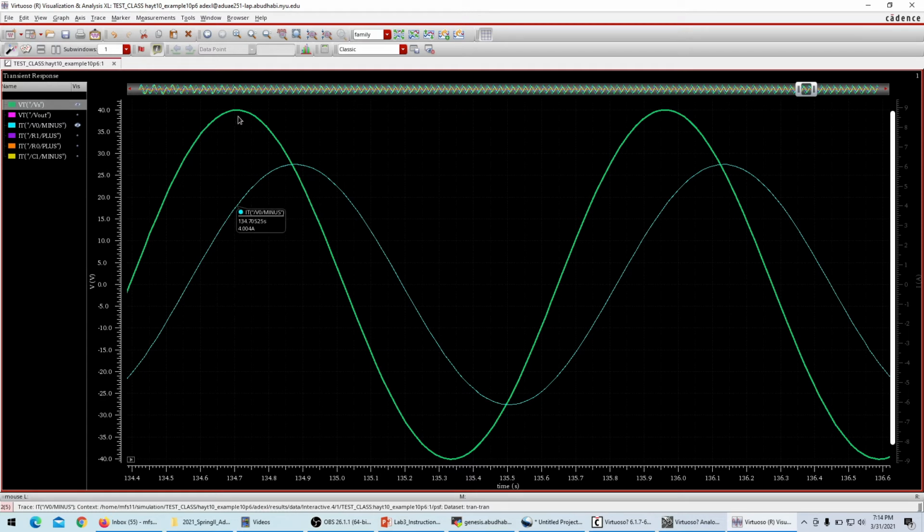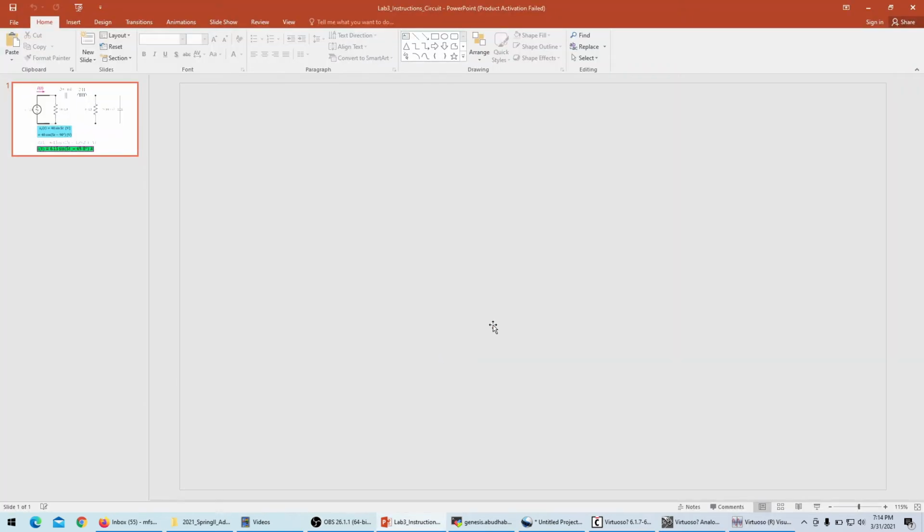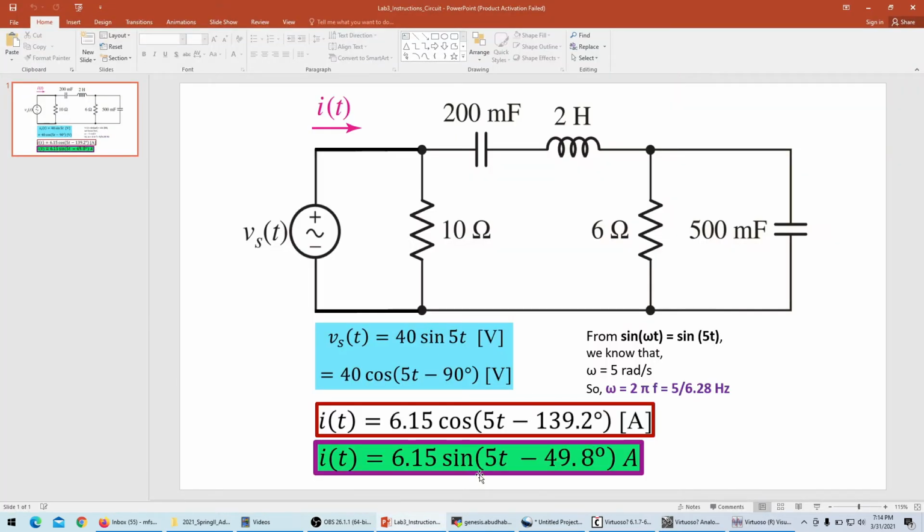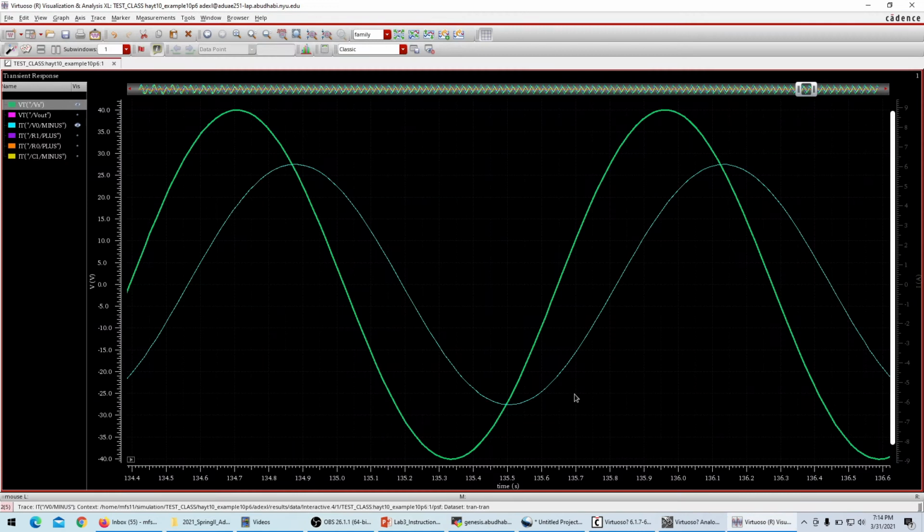Again, this is in the middle and it represents 90 degrees. This is three squares. So three of these rectangles represent 90 degrees. Half of it, which is 1.5, represents 45 degrees. And since this cyan wave is a little bit ahead and not exactly in the half, we can safely say it is 45 plus degrees, which I would say is 50 degrees. Thus kind of confirming our phase angle shift for this plot.